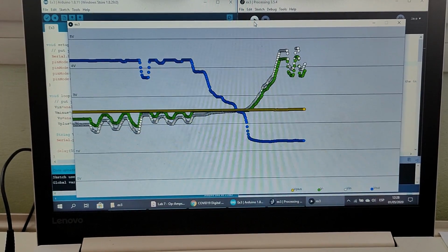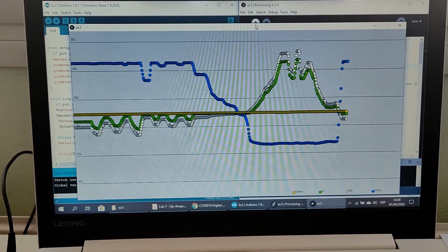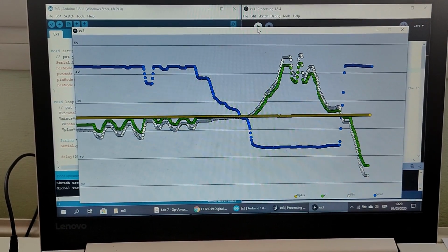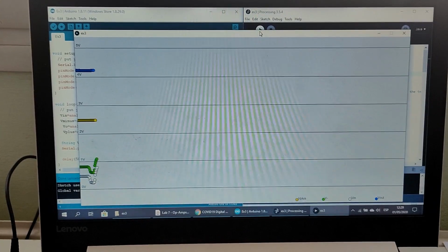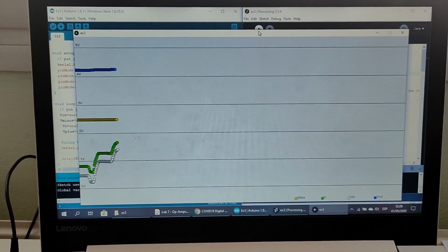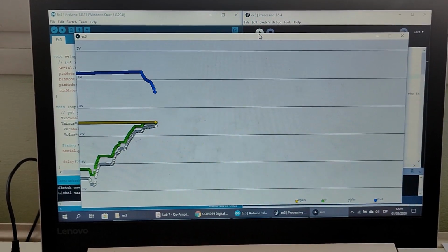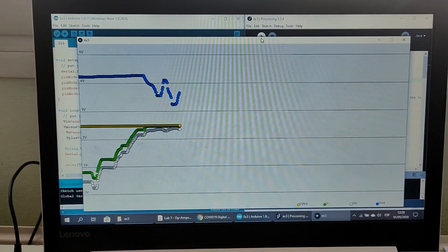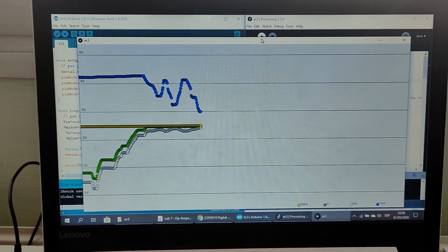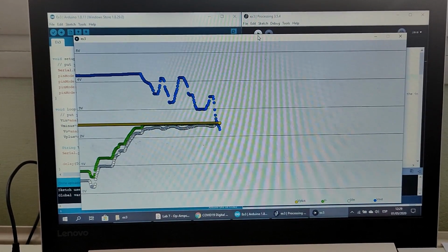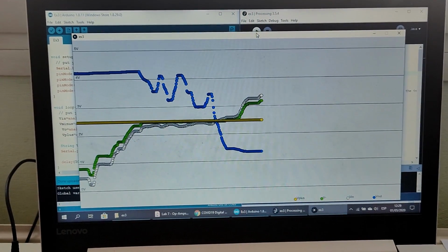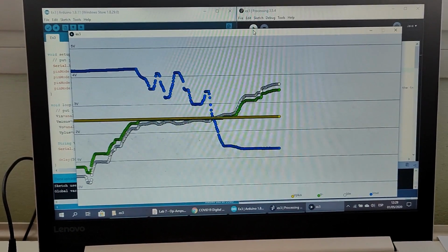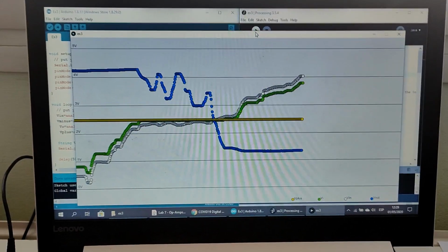If we go to values too high or too low, it would not vary because of what we explained about the Arduino only working between 0 and 5 volts. So this would only work for really small values. As we see here, we were inverting it, but we were very close to the ground, so it would vary the voltage output between around 1.5 volts and 4 volts.